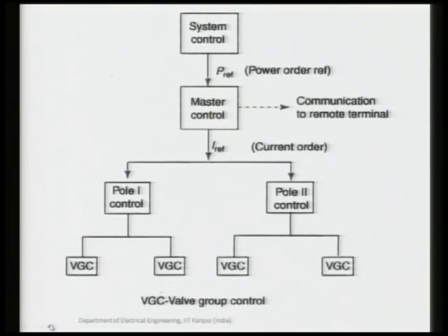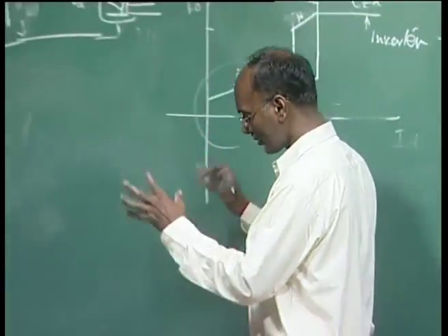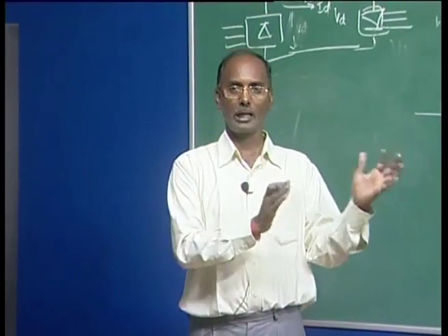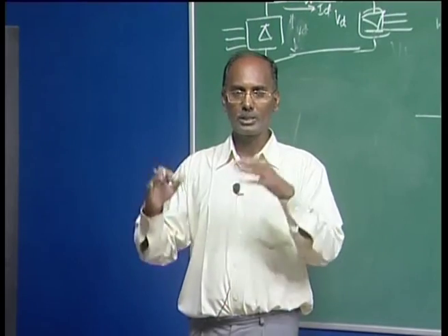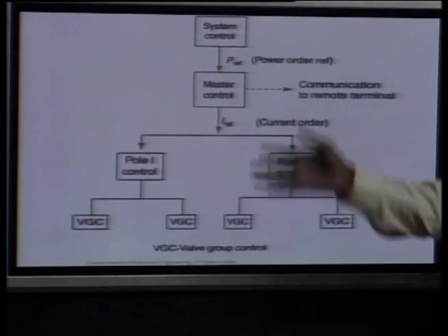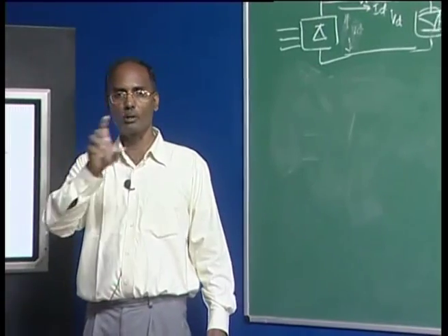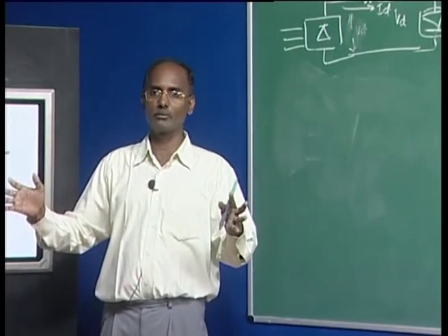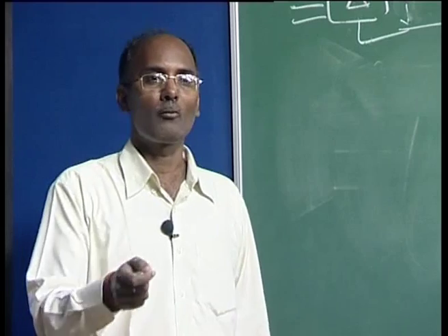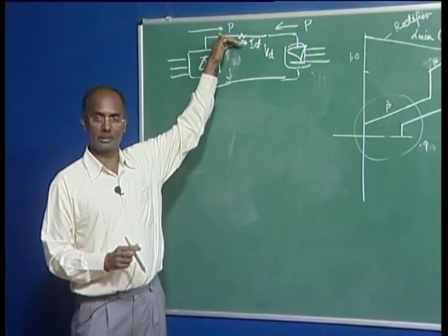Now in the total philosophy, it was the characteristic first, and once this characteristic is there, then you have to design a controller for all these characteristics, both rectifier as well as inverter. Now you can see the control hierarchy. Here we should have a complete system control for both the inverter and rectifier end. What is your philosophy, what is the power setting, how much you are going to do. This is what we call the whole system control, because based on this you decide what will be the power reference, how much power you want to flow in this line in the normal case.